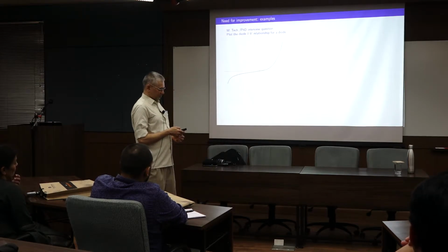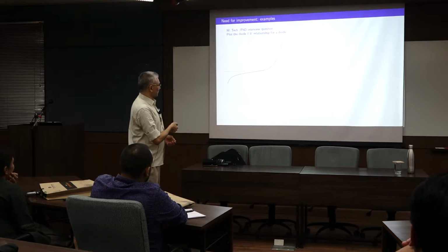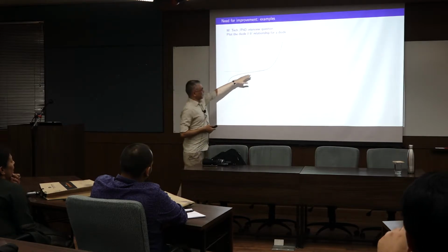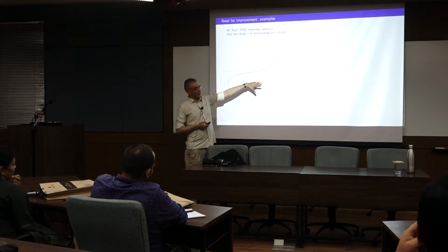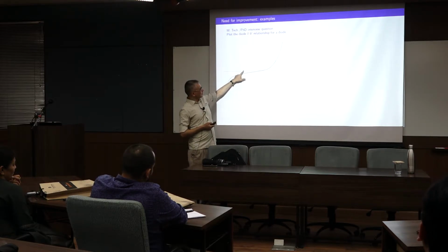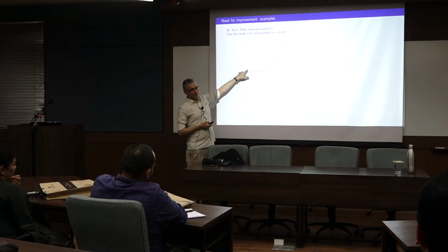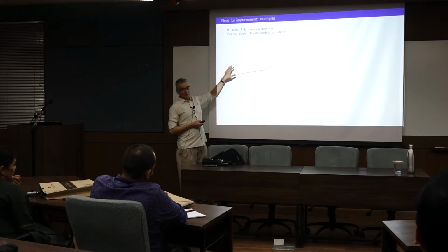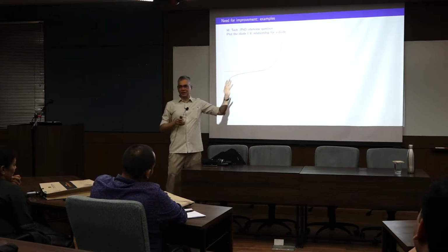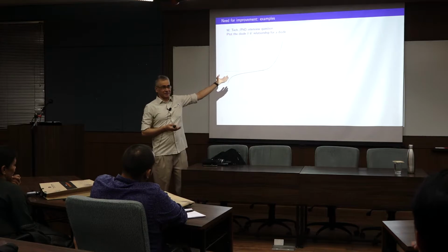Normally what textbooks show is that they plot this in milliamperes and they plot this in nanoamperes or microamperes, and then this sort of looks reasonable. And then this axis is also different. If this is 0.7 volts, then this would be 5 volts, 10 volts, and so on. But the students have forgotten all of that, and this is what they draw. It doesn't make any sense, right?